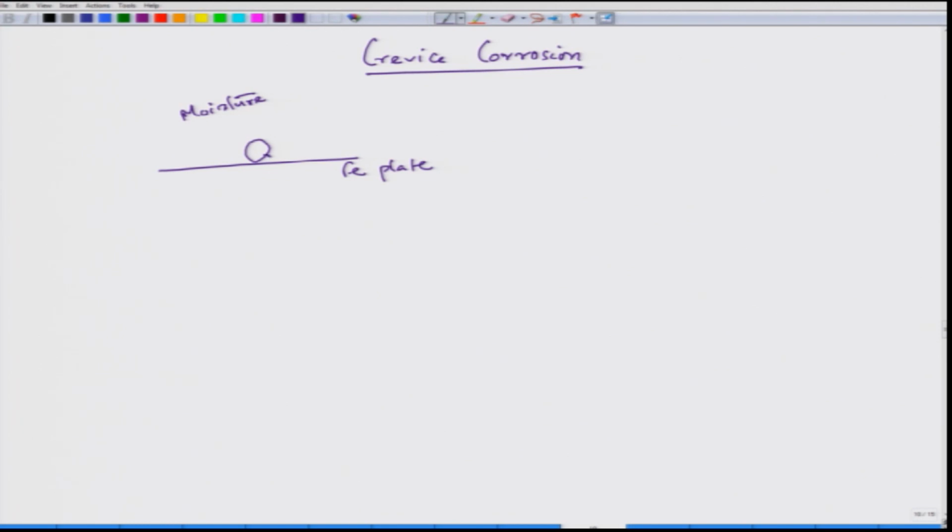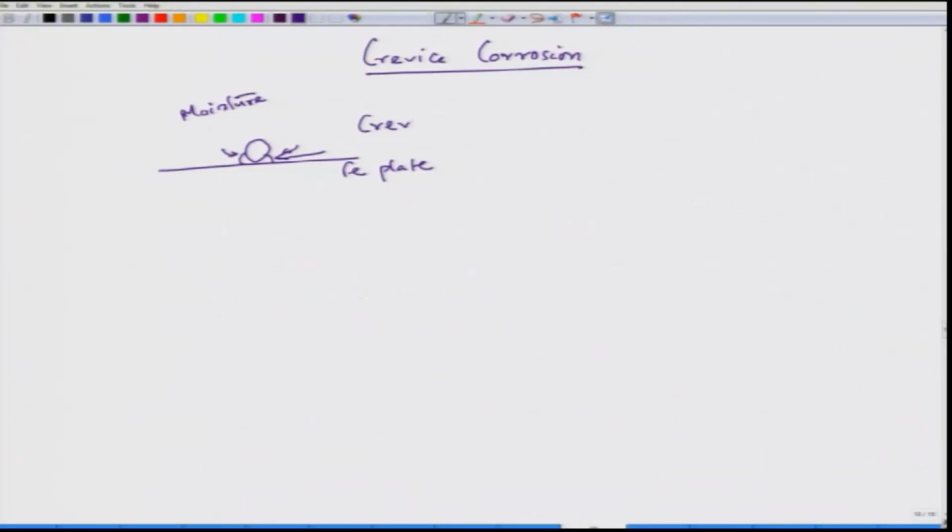now of course, in these two regions there could be a possibility of water ingress, and this water ingress could be possible if this opening is wide enough, so that the water can overcome the surface tension resistance to get into these sections. So, this is a small gap where moisture can sit or enter. And interestingly, once moisture goes into this gap, it remains stationary or stagnant. This is a particular example of crevice. This is also a crevice.